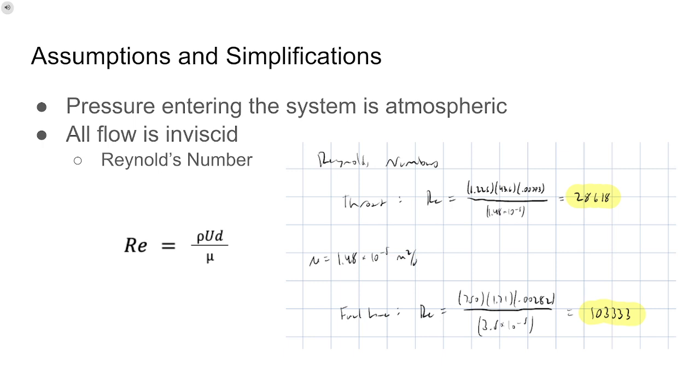Based on our calculations, we found that our Reynolds numbers were high, and we know that because the fluid mixture is zooming through the tube over a short period of time, viscous effects can't diffuse too far from the surface. And also because the fluid mixture in this case is predominantly air, the viscous effects are easy to neglect in comparison to using a more viscous fluid.